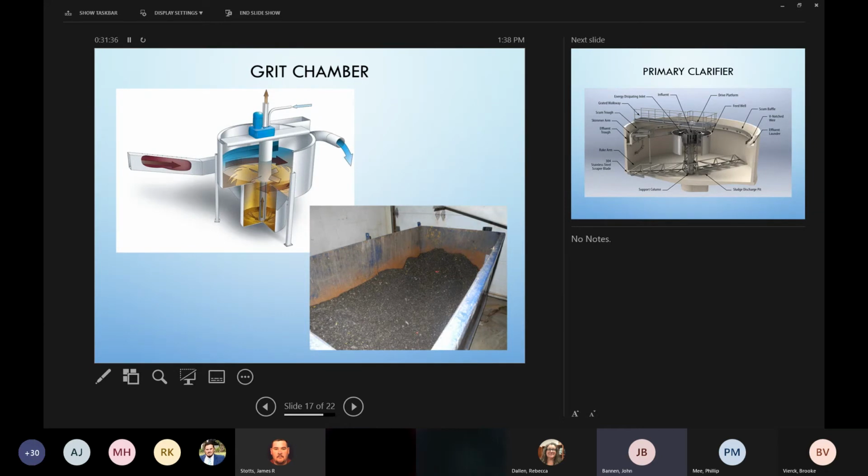to settle. But when we allow the grit to settle, if we have a floatables and a grease problem at the plant, we are going to get those floatables, and that material is going to come out with the water flow out the top of our grit chambers or continue to flow through the system. And the grit chamber is not made to remove that grease and settable or floatable material from the process. It is designed specifically only to handle the grit at the bottom. So there's no means at the top of our tanks, at the top of our materials, to actually remove those floatables unless we actually have to do it with a maintenance event, in a special occasion.